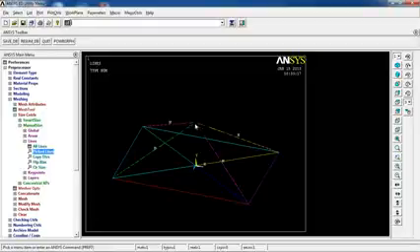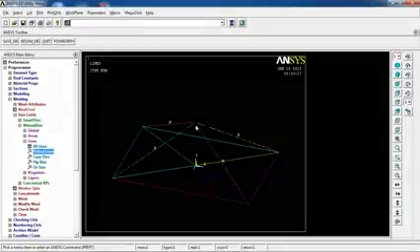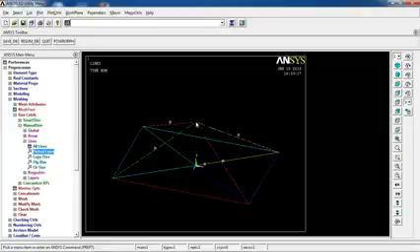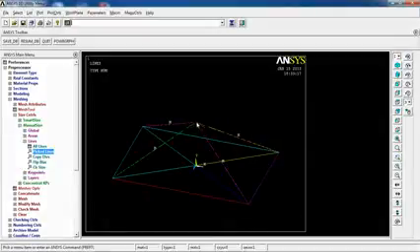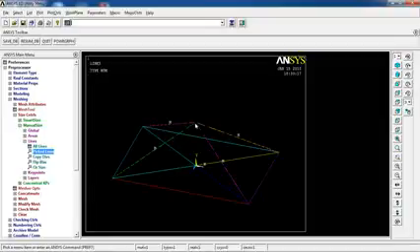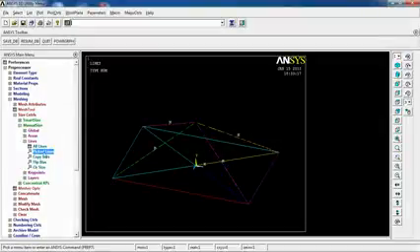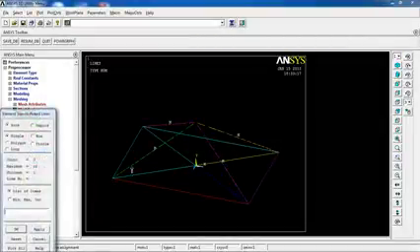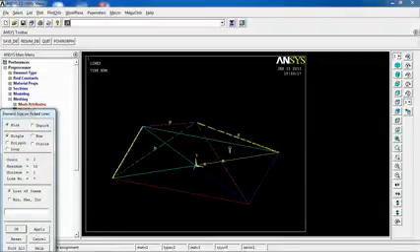Because initially I wanted to make this mesh look like this, finer at this end and coarser at these ends. So that's why I was picking this key point first and the other key points second, to make sure that the beginning of my lines was being placed at key point 1, and the end of my lines were at either of these 2 corners of this rectangle. I come here again, pick these lines now. If I can pick this line, which is a little tough.